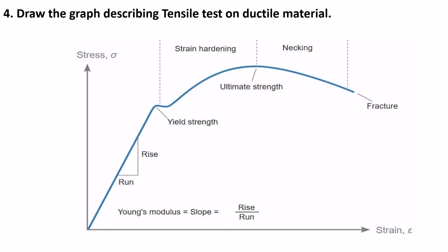After that it is linear. Stress and strain are directly proportional. It is linear. After that it is non-linear, up to a certain limit called the elastic limit. If you remove the stress or unload, it will regain its original point. So it is very close to the proportionality limit. The elastic limit and the proportionality limit are very close.